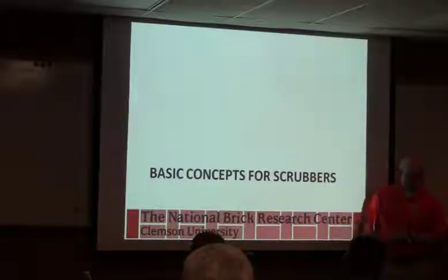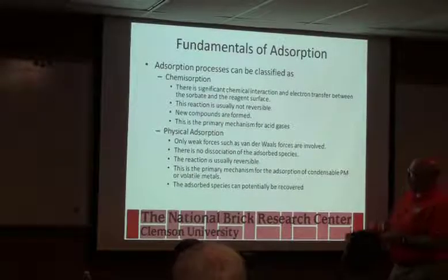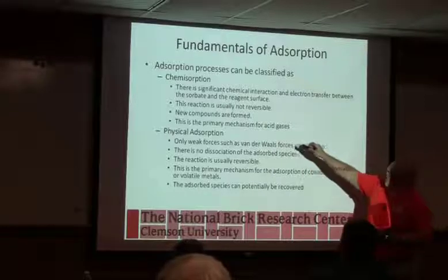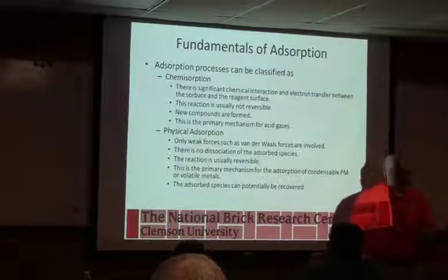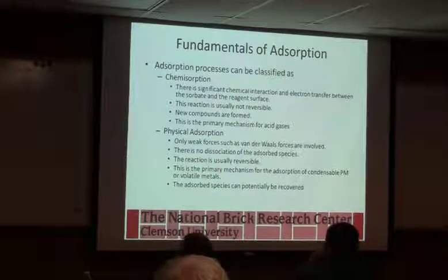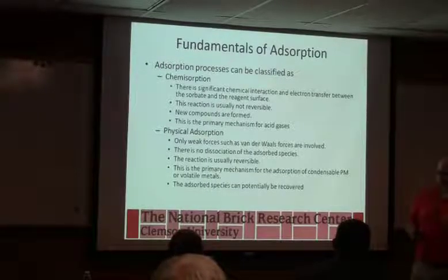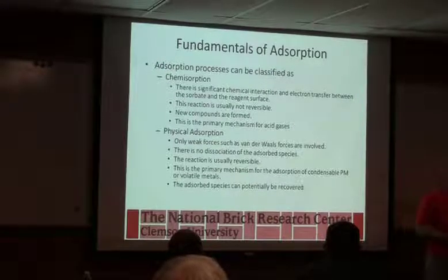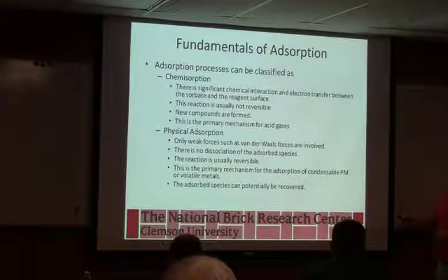So just a little idea on how scrubbers work and what goes on in there. There are two types of absorption that take place. A chemical absorption, that's mostly what we're seeing with the HF. It wants to react. When you take an antacid, that is a basic material. It's a base. We're combining that with the acid in your stomach and you make salt and water. You neutralize it. We're doing the same thing in a scrubber. We've got your limestone, which is basic, and you're putting acid gas on it and you're making something that's neutral. And we're reacting to do that.